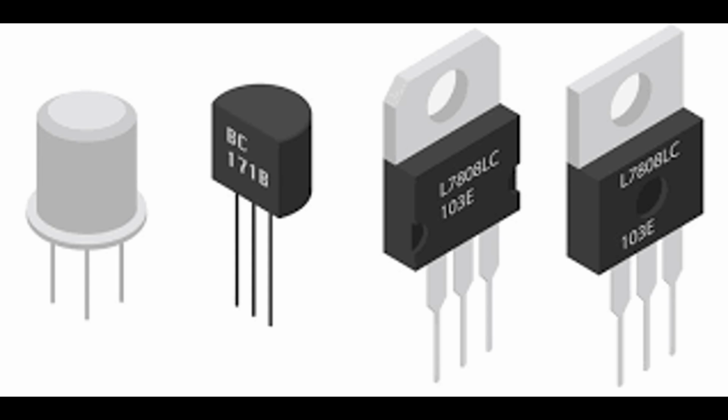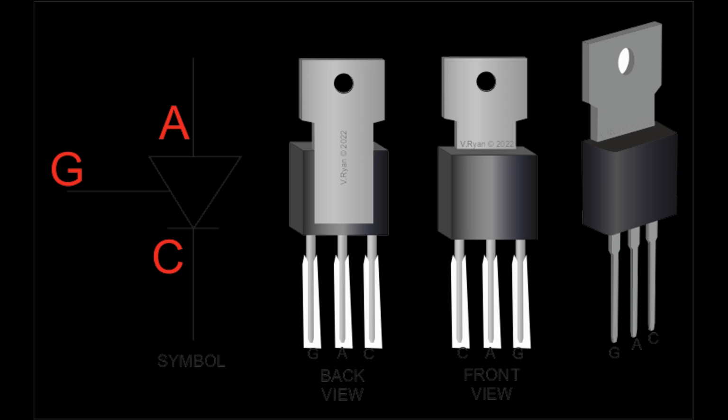Structure and operation. Structure. Layers. The SCS has a 4-layer PNP structure, similar to an SCR. Terminals. It has 4 terminals. Anode, A connected to the outer P-type layer. Cathode, K connected to the outer N-type layer. Gate, G1 connected to the inner P-type layer, used for turning on the SCS. Gate, G2 connected to the inner N-type layer, used for turning off the SCS.